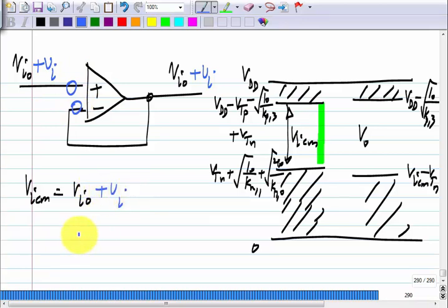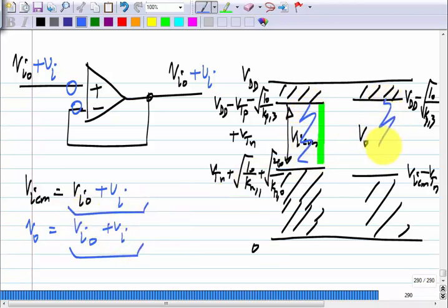Okay. So, if you have a non-inverting amplifier, this is always the case. And then what is the output voltage? That is also Vi0 plus Vi, the total output voltage. So, you have to make sure that both of these are in their respective limits. Okay. Then you choose Vi0. So, one of the goals usually is to maximize the amplitude of the lowercase Vi, the input signal that you apply. So, you have to choose Vi0 such that you can apply the maximum value. Okay. So, that is the philosophy. I did not take the numbers, but if you have the numbers for all these transistors, you can calculate and find that out.